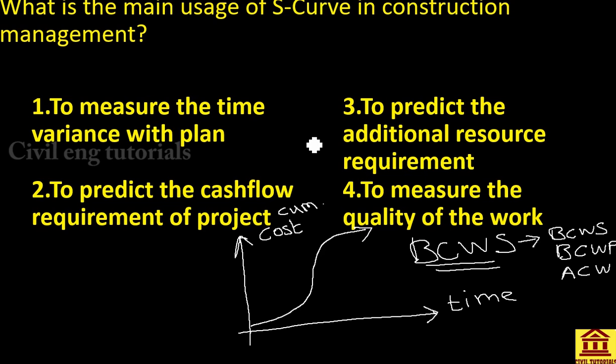So the main usage of the S-curve in construction management is to predict the cash flow requirement of the project.